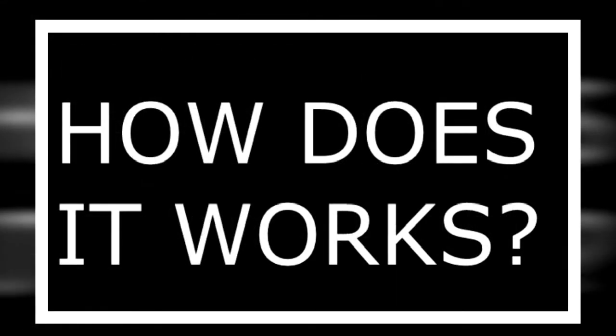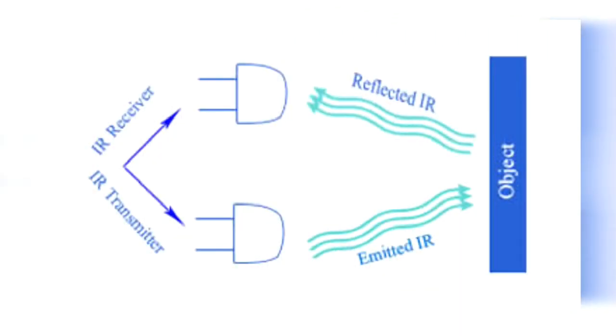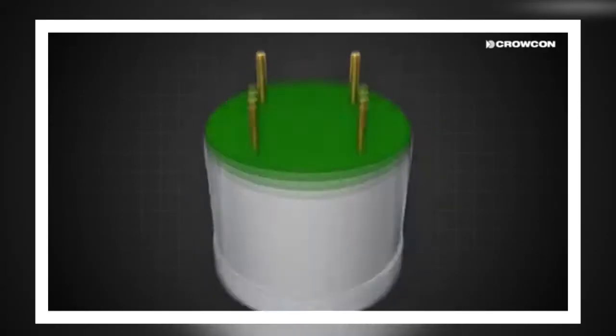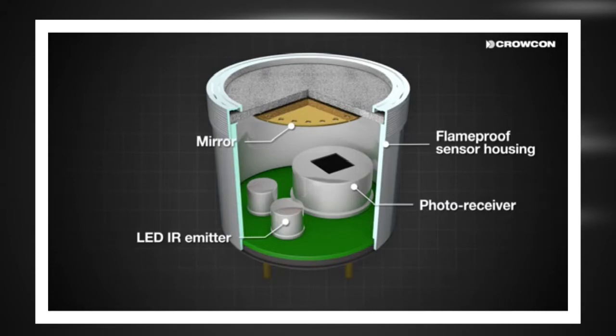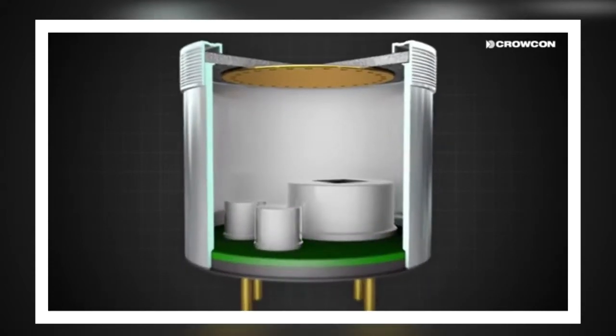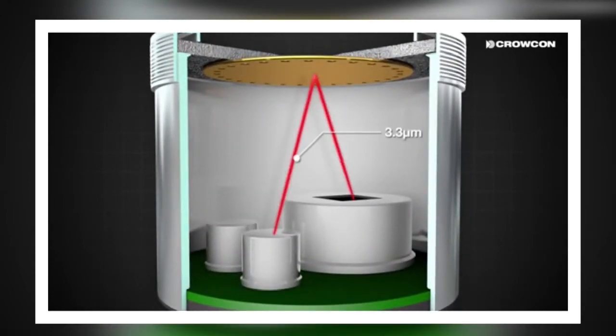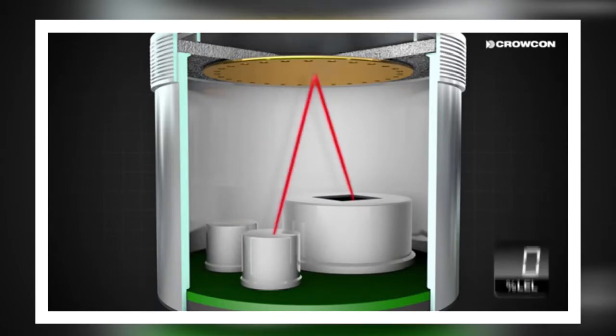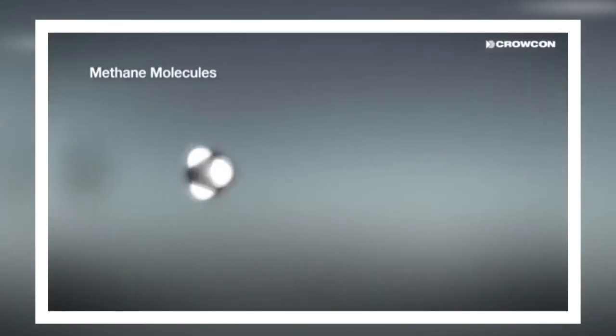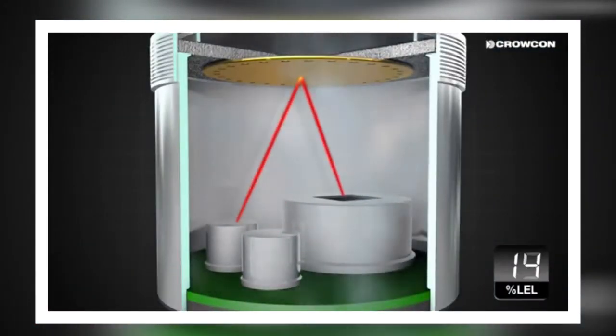How does it work? When the IR receiver is subjected to infrared light, a voltage difference is produced across the leads. The low voltage produced can hardly be detected, and hence operational amplifiers, op-amps, are used to detect the low voltages accurately. Measuring the distance of the object from the receiver sensor, the electrical property of IR sensor components can be used to measure the distance of an object.